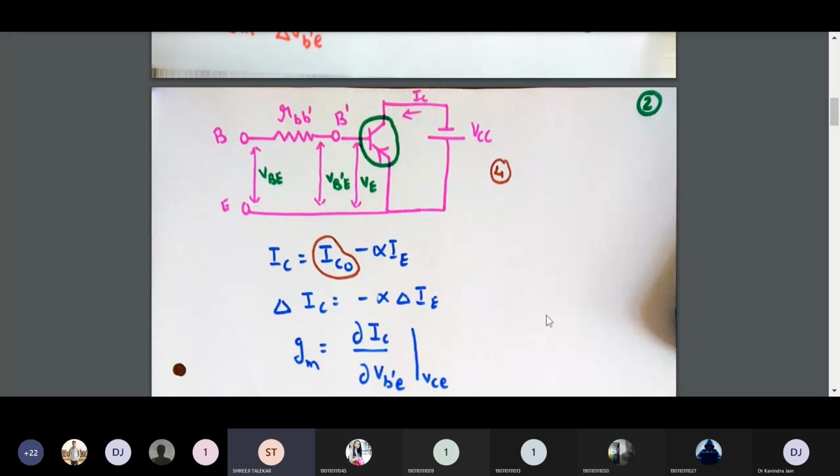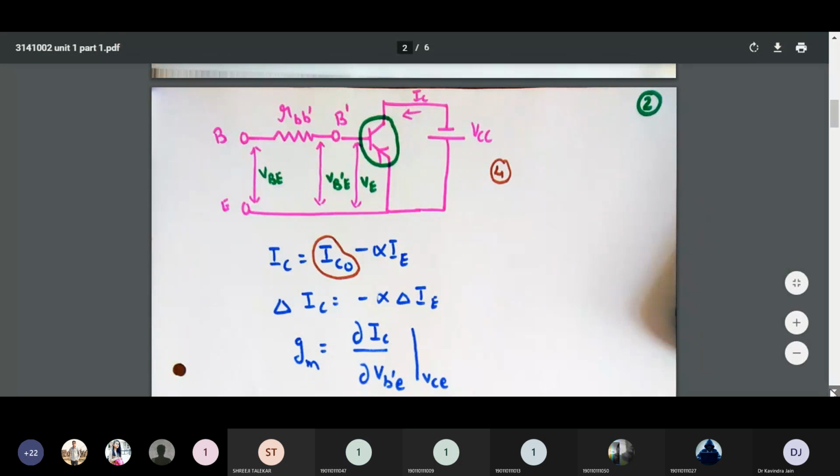Hello 47, am I audible? Yes, sir. The delta IC, if I replace it by minus alpha delta IE, so what will be my new gm? Minus alpha delta IE by delta VB'E. Okay, delta IE, not IC. Yes.